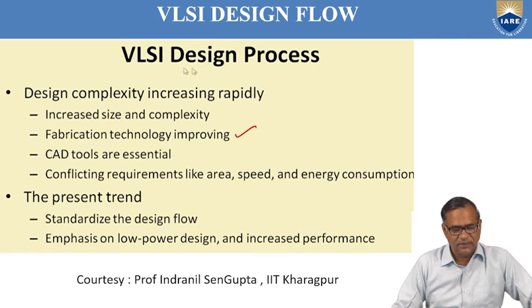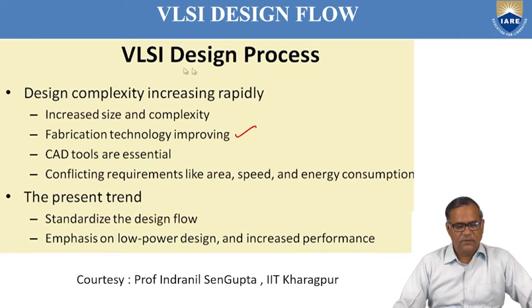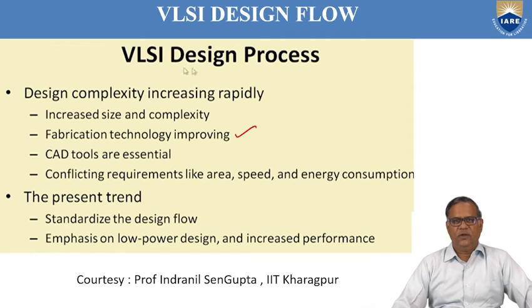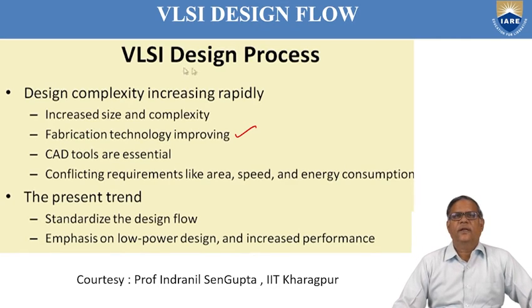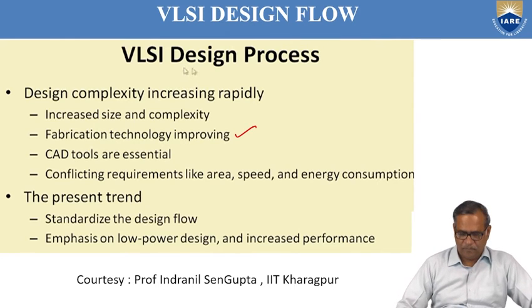So what is the present trend? The present trend is to standardize the design flow. The emphasis is on low power design with increased performance. Why do we go for low power design? Because nowadays most of the systems are battery based. When the systems are drawing power from the battery, it's always advisable to aim at low power so that you get maximum backup time.